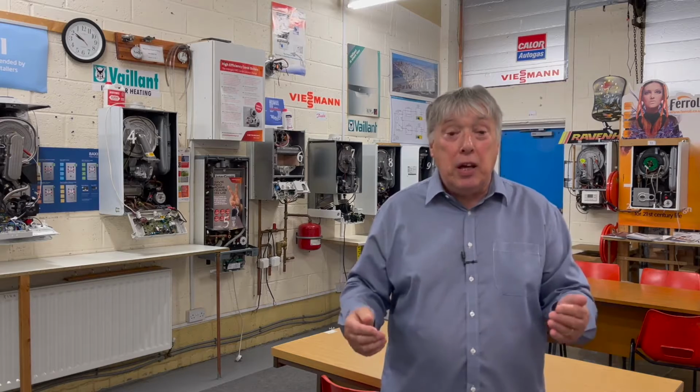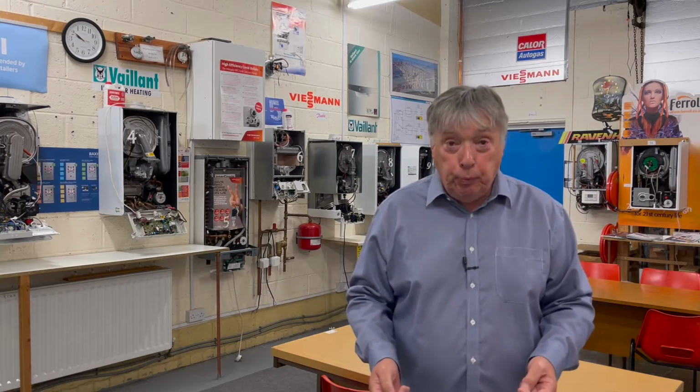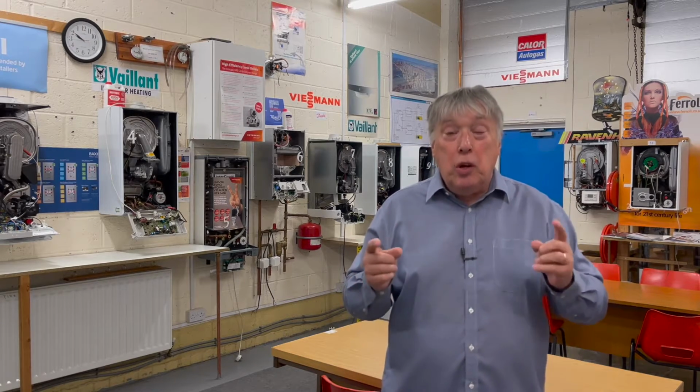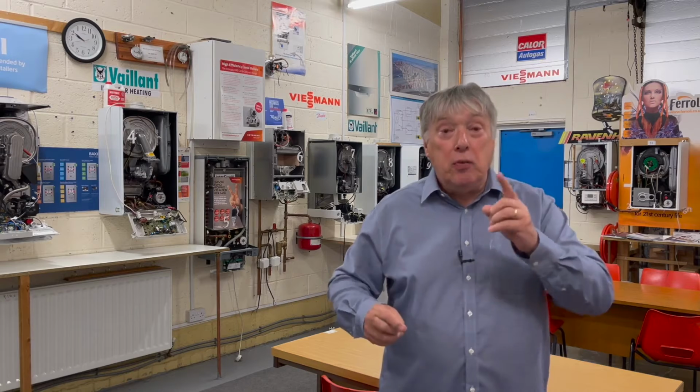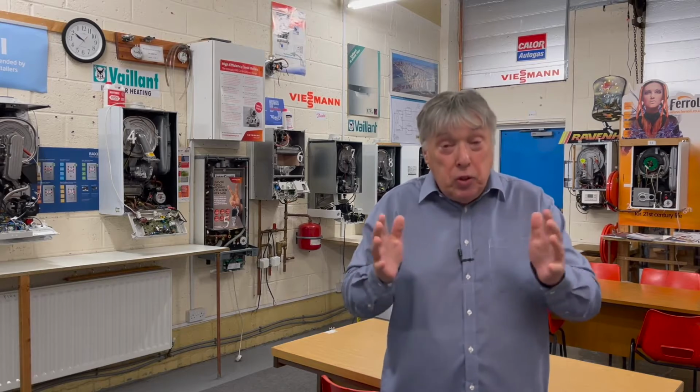Obviously, we're all a little bit different, and some people may say calculate to 22 or even 24 degrees, which is going to be expensive, obviously. The 20 degrees we calculate from the heating flow to the heating return on the boiler, and there has to be a 20-degree rise or difference.